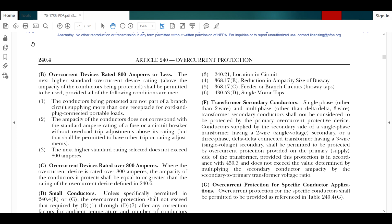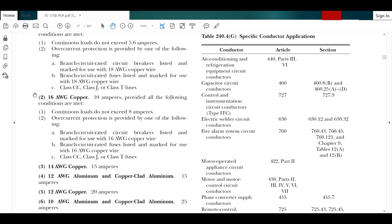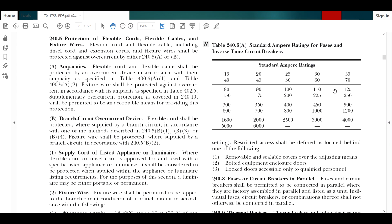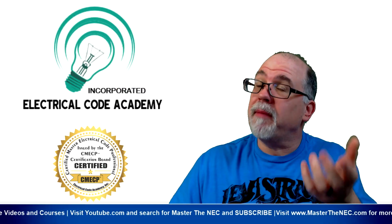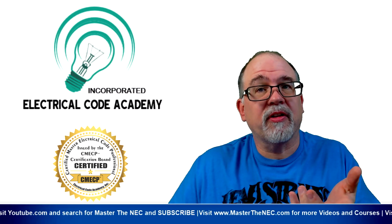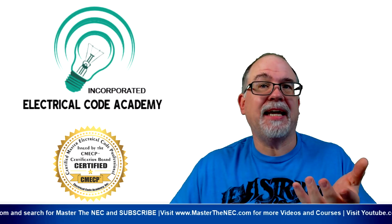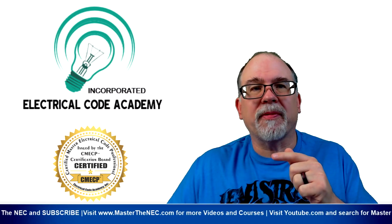In this case, I want to go back down to our table. It didn't correspond, so that's why we ended up at 125. And yes, based on the rules of 240.4(B), we are protecting that conductor at its ampacity. So we're good to go. So in theory, at this point, we're not only protecting the primary of this transformer, but we're also protecting the primary conductors as well with this one device. Okay, so that's how we're doing that. Now we're going to learn how to size the overcurrent protective device on the secondary.